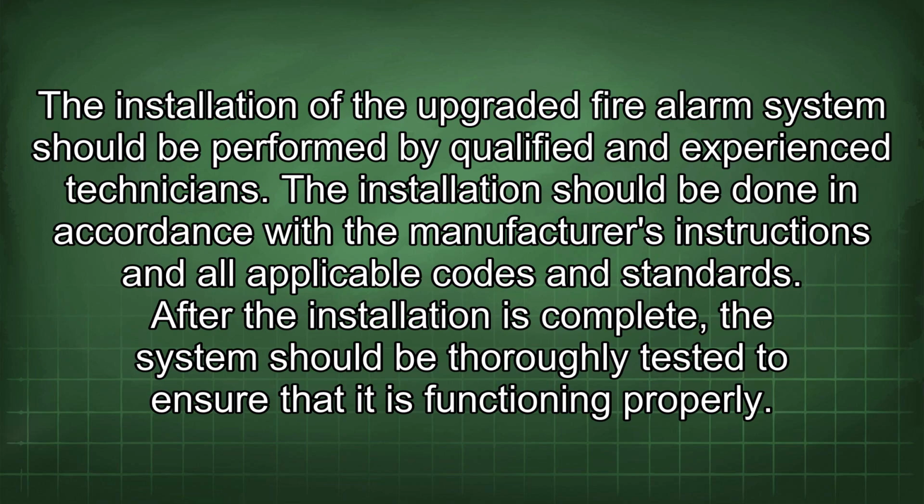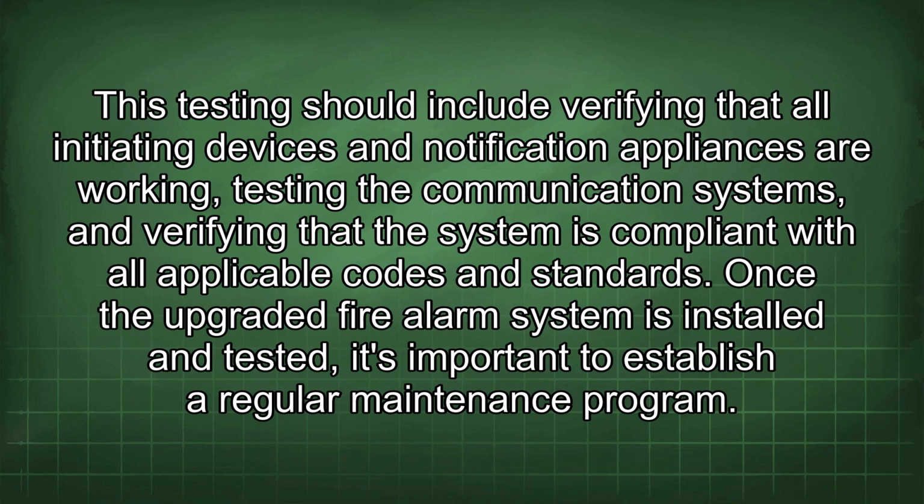The installation of the upgraded fire alarm system should be performed by qualified and experienced technicians. The installation should be done in accordance with the manufacturer's instructions and all applicable codes and standards. After the installation is complete, the system should be thoroughly tested to ensure that it is functioning properly. This testing should include verifying that all initiating devices and notification appliances are working, testing the communication systems, and verifying that the system is compliant with all applicable codes and standards.